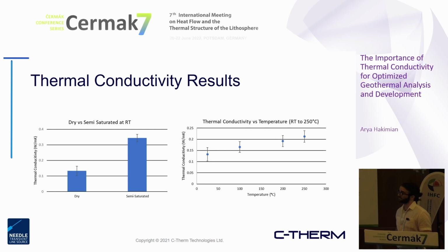These measurements simply show that, of course, under a saturated condition, you're experiencing a much higher thermal conductivity compared to the dry matrix. If we think about the sand sample, the spacing in between the individual particles can be saturated and devoid of that airspace. So by the water coming in and filling in those different spacings, we are seeing a higher effective measurement of that thermal property.